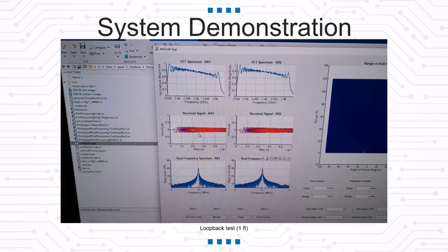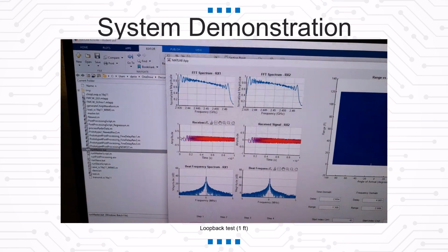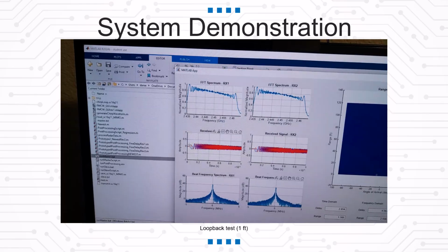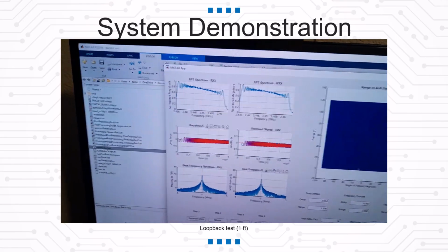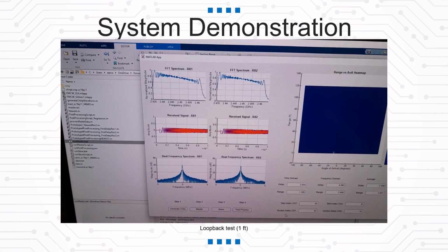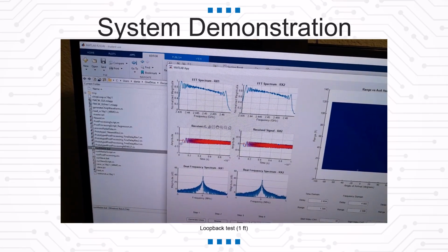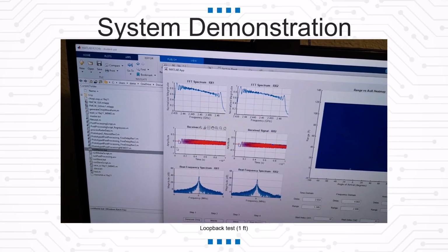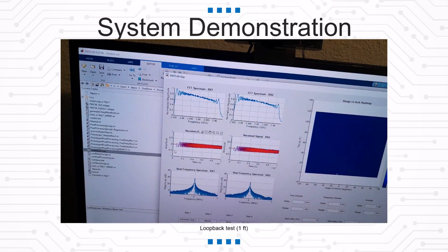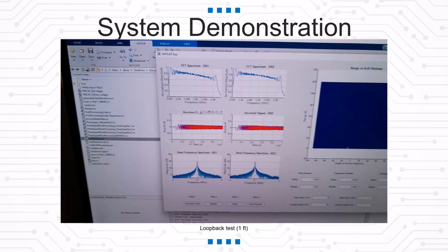So then in the time domain, the information coded in here is the distance to the target, or for us it's just the propagation delay of that 1 foot cable. And the system delay that we entered, this 42, helps get rid of some of that, because there's an inherent delay from the hardware through that trigger cable, through the GPIO pin.